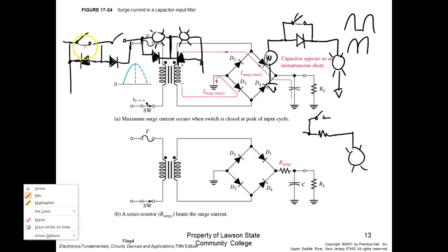It's like when you get into AC and you start dealing with capacitors and inductors, you'll actually get more voltage drop in a circuit than you have applied to it. If you hadn't had AC yet, you're going to. So you can come up and measure, you got 50 volts applied to the circuit, and you measure across your resistor, and you got 30 volts, and you measure across your capacitor, and you got 30 volts, and you add them together, you get 60 volts, and you're saying, but I've only got 50 volts applied. That messes them up too.